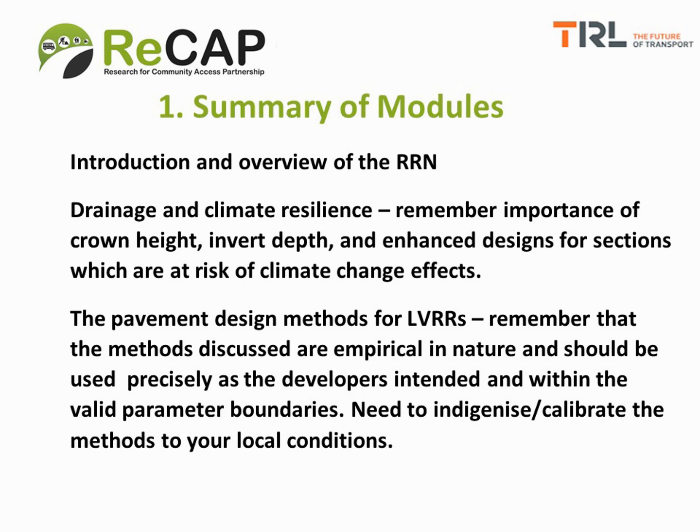The third module covered the pavement design methods for low volume rural roads. And here we want you to remember that the methods discussed are empirical in nature and should be used precisely as the developers intended and within the valid parameter boundaries used to develop the methods. You should also note that it may be necessary to indigenize or calibrate the methods to your local conditions.